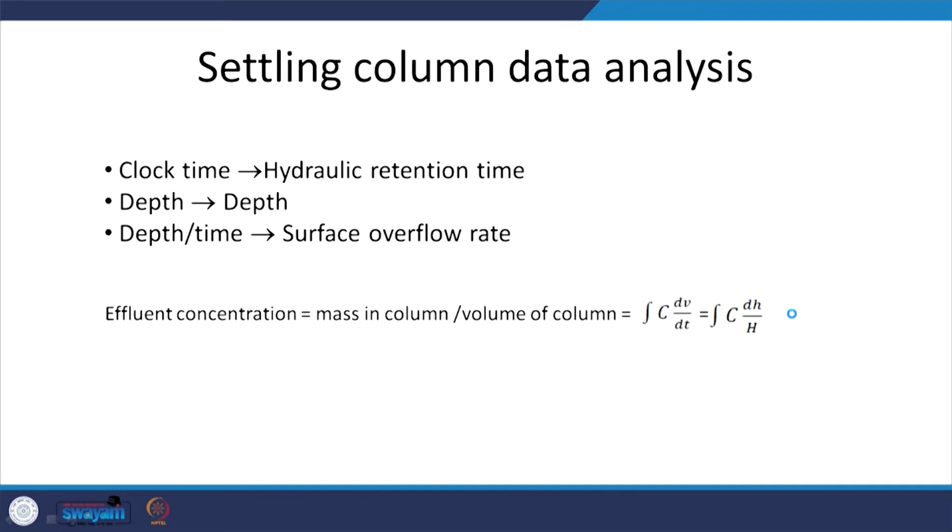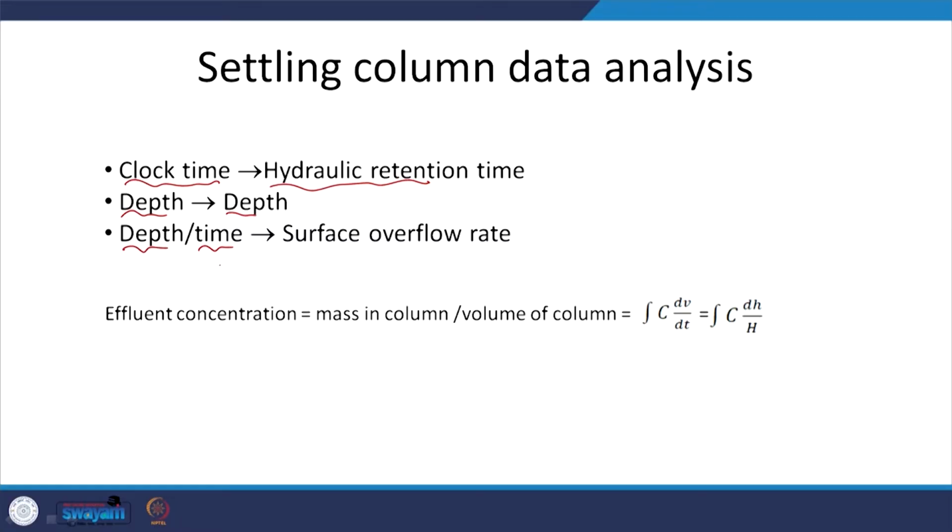As I mentioned, the clock time in your settling column is similar to your hydraulic retention time, and the depth is the same as the depth in your sedimentation basin. The depth per time will give me an idea about the surface overflow rate.